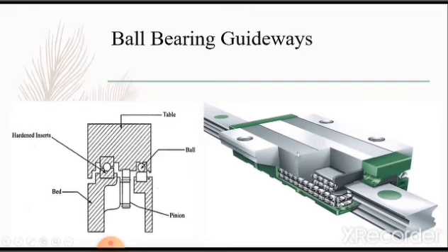Correct. So these balls, this is a slide and this is a slide guideways. These guideways are provided. In the guideways, the balls are already filled, and when you move the guideways in the XY direction or any direction, in the X-axis or Y-axis, these balls will provide them a smoother motion. Correct. There is one benefit of these ball bearings, that it does not have a stick and slip motion.